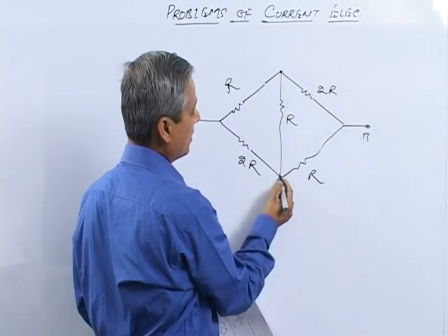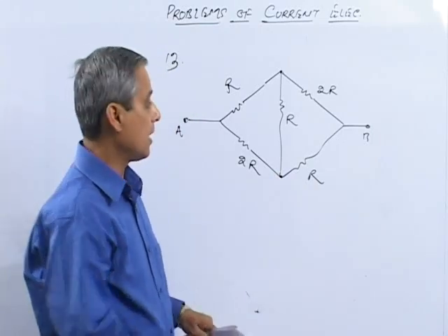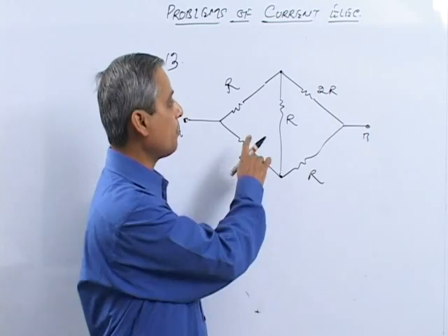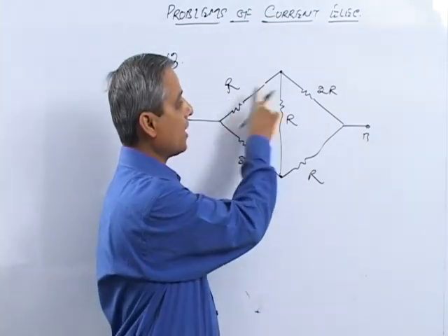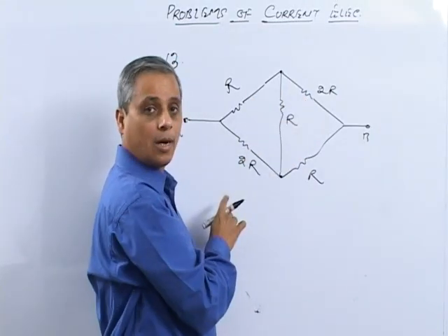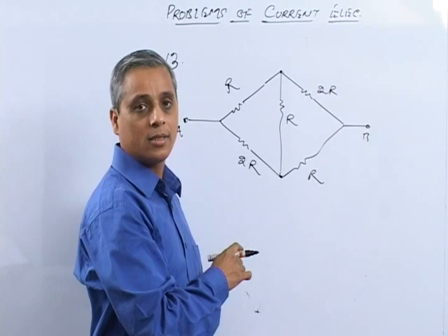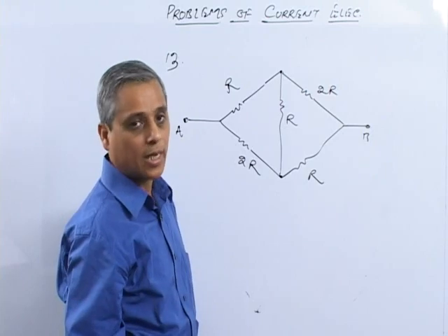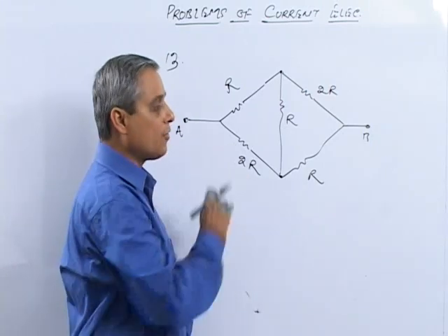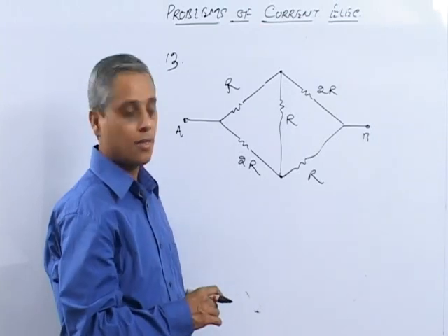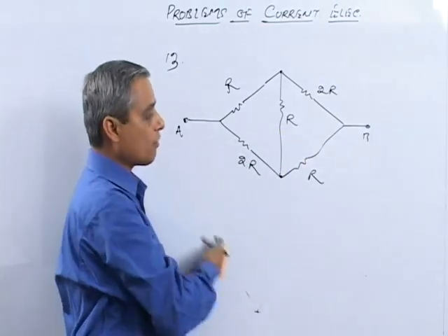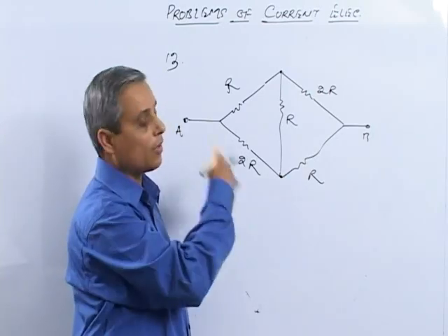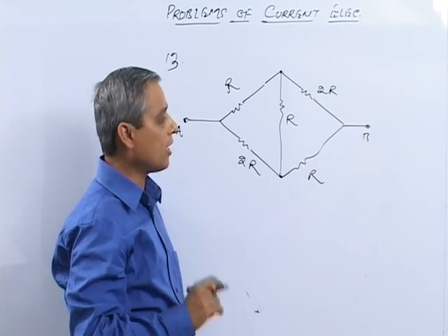Here you understand that the circuit represents basically a Wheatstone bridge, and this Wheatstone bridge is not balanced. It is basically 1:2 for the upper part and 2:1 for the lower part. So the circuit is unbalanced. And in an unbalanced Wheatstone bridge, you can find the equivalent resistance between the two terminals by Kirchhoff's laws. You connect a battery, find the current following 3 loops, and so on. That is quite a long method.